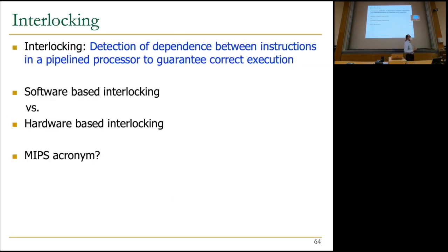This ISA is designed to become a producer of microprocessors without interlocking pipeline stages, without hardware interlocking, they meant actually. Okay, but the software still needs to do interlock. So that was the goal, but the reality is it's very difficult to do that in software completely. So all of the MIPS incarnations after the first ones have done interlocking in hardware. So their name was obsolete, or at least their name was not consistent with what they did in the end.